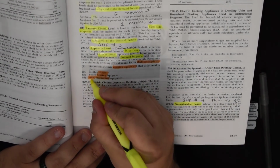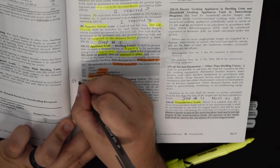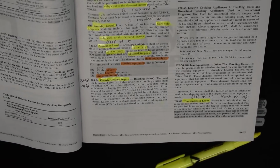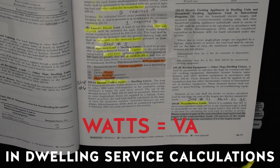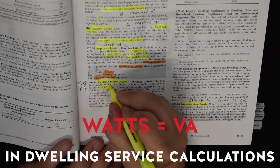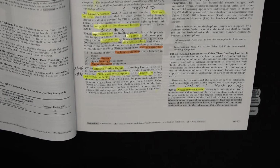220.54 takes us, again, we're not jumping around, it's all right here together. Highlight electric clothes dryers and write step number 6 beside it. It goes on to say electric clothes dryers, dwelling units. The load for electric clothes dryers in a dwelling unit or units shall be either highlight 5,000 watts or volt amps. Highlight volt amps, because watts and volt amps according to this part of the code are the same. We're not going to differentiate watts and volt amps. It says or the nameplate rating, whichever is larger. Highlight nameplate and then highlight whichever is larger.